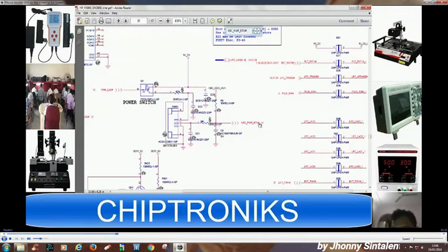So you can see this is hash, that means 0 volt would go there to the IO controller, because right now when you do not press the power button, there is no path, so there is 3.3 volt. So before pressing the power button, what you have to check at this point is that your 3.3 volt is coming, and this is coming from the LDO, right, AUX. So if 3.3 volt is coming, then you can ascertain that your LDO volt is okay.